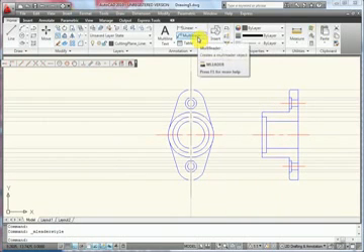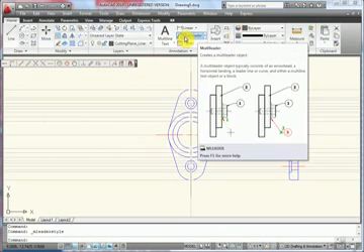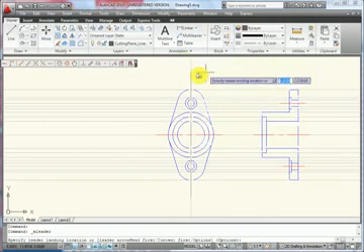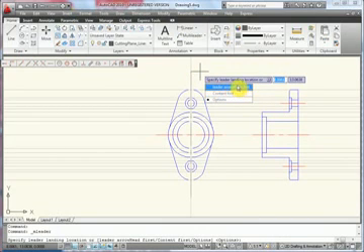We'll now go up to the multi-leader tool by just pressing it. And before we select anything, we're just going to press the down arrow, which will give us a few options. And we want the leader arrowhead last, not first. So we don't want to check this. If for some reason you come upon it and it gives the option to give the leader arrowhead last, that's when you want it.